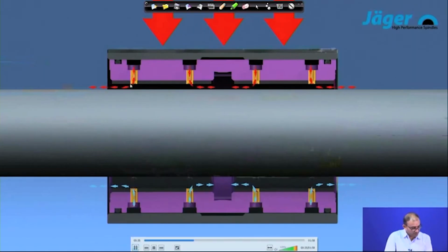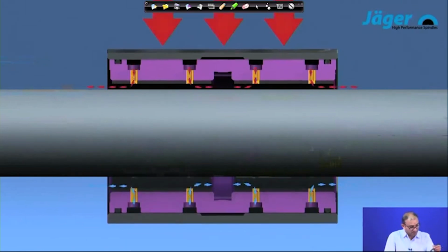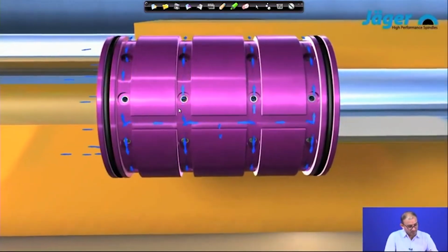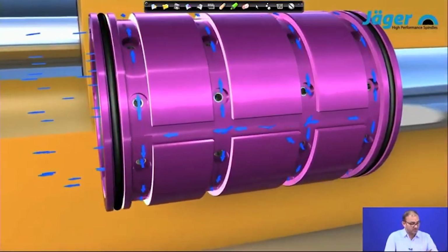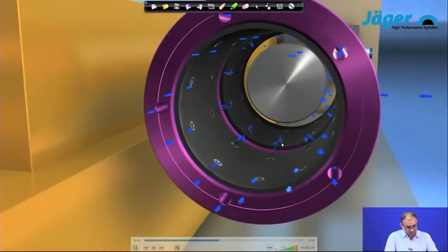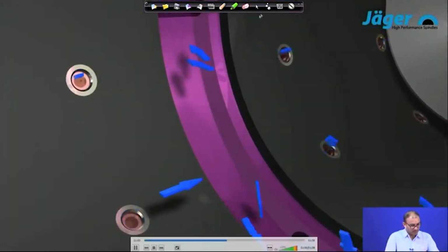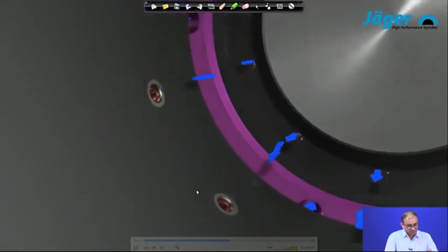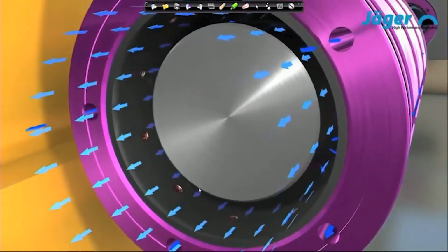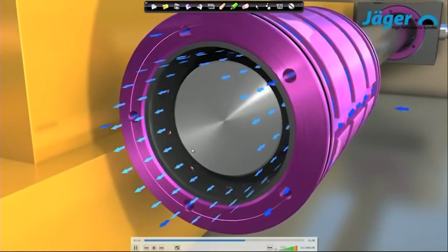Right. So, in this location this is a red color, that means high pressure, again both things are maintained, now both things are in blue color. Again it will go down, this becomes less high pressure, this is a low pressure zone, again it will match the part. So, in this way what is happening, this is a self-adjusting bearing. Wherever there is a pressure difference, it will maintain that pressure difference by the pressure regulator of this particular air bearing. So, this is how it is useful. And once there is no contact of this part, then you can easily move this shaft to and fro or you can move the table to and fro, that is up to your application which one you want to make stationary, which one is a movable component, correct.